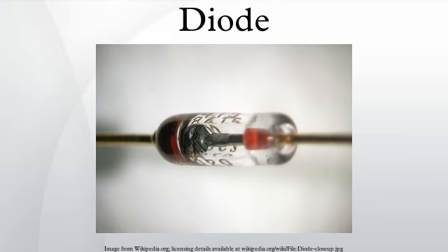Schottky diodes are majority carrier devices and so do not suffer from minority carrier storage problems that slow down many other diodes, so they have a faster reverse recovery than PN junction diodes. They also tend to have much lower junction capacitance than PN diodes, which provides for high switching speeds and their use in high-speed circuitry and RF devices such as switched-mode power supplies, mixers, and detectors.